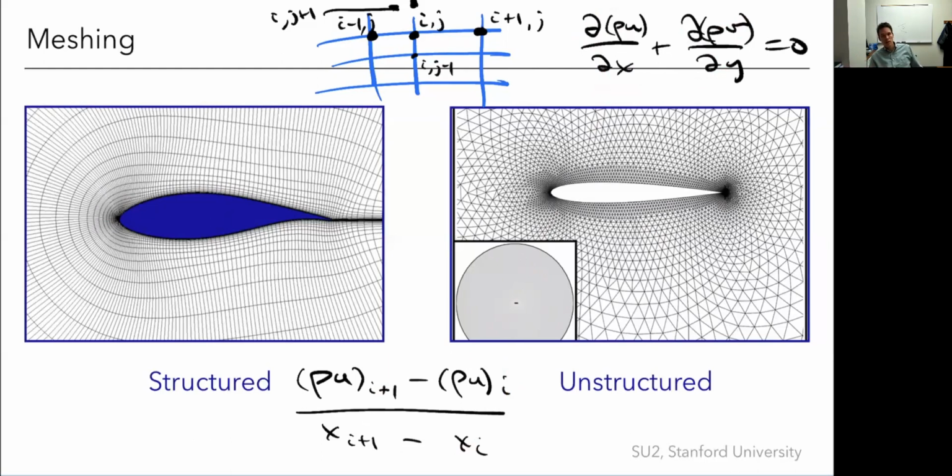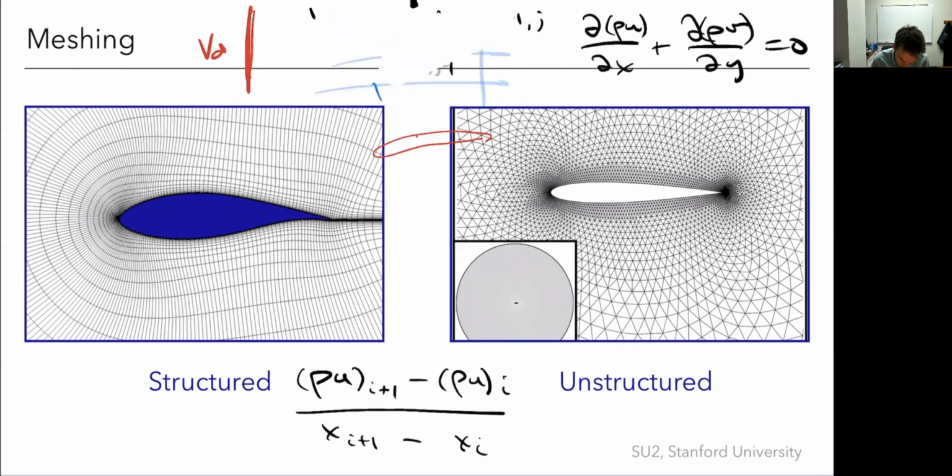And they won't be right because my prediction for the value here is based on the one here, but that one's not right either. But I get an update, right? And so then I can do it again, and I do it again, and I do it again, until I get a converged solution. And they're driven by, for example, let's say I have a free stream. I have some known velocities here, way upstream, and they're being fed through here, right, across the domain, and say I've got a body over here, and I have to get the right boundary condition there. So basically, my boundary conditions are driving the solution, and eventually that will all converge. So this is called a finite difference approach. Another approach called finite volume is I could have, say, the same kind of domain.